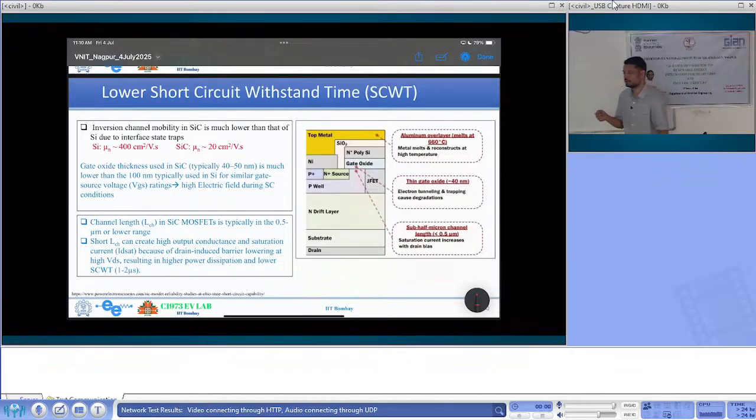In power electronics, although we always try to make sure there is no overlap of the two switches turning on, we always create a dead band, so one switch turns off, then another one turns on. But in reality, there is a short circuit which happens once in a while. And therefore, we have a protection circuit which can detect and avoid that short circuit of the two devices.